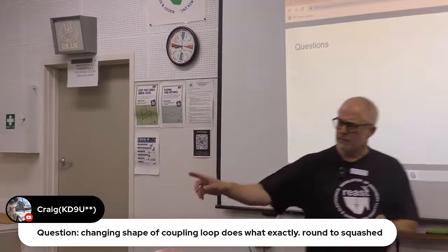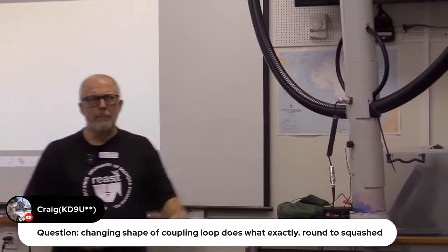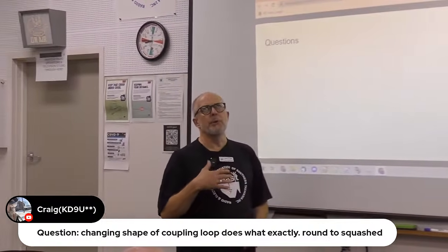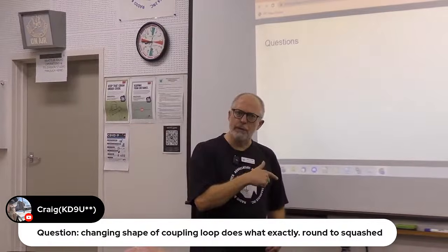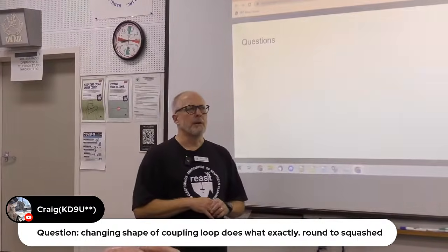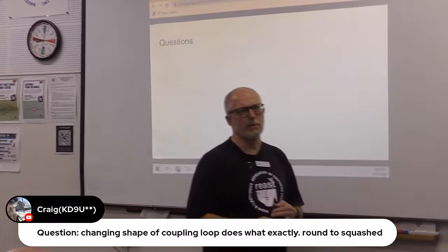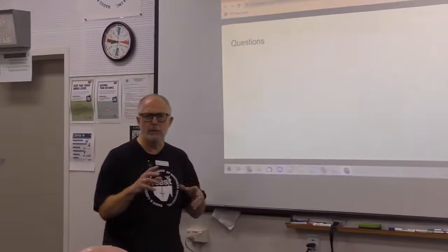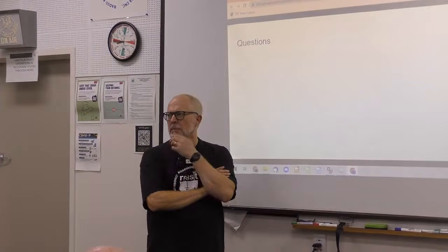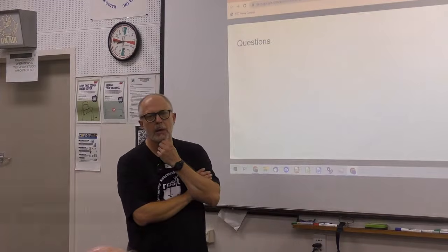Well and truly. And in fact, I've done that. I've actually brought it closer to the loop to improve the SWR at the lower frequencies. At the higher frequencies, it was fine. The coupling was great. But at those lower frequencies, I brought the coupling closer to the loop, and it improved things. Not much. You're talking about a quarter of an inch, quarter to half an inch. Not much. And the next question is, does a variable capacitor remove the need to change out the coupler?